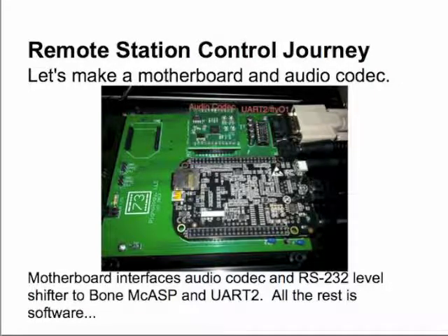One of those UARTs is broken out here, which is TTY01 or UART2 of the BeagleBone, which just has traces coming into the UART here. This is the level shifter chip here. I also put an XB footprint on here, which we'll talk about in a little bit.